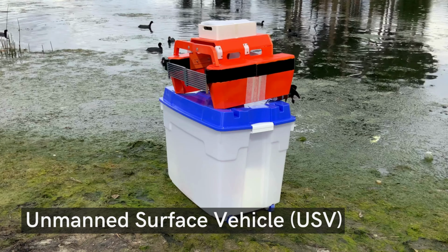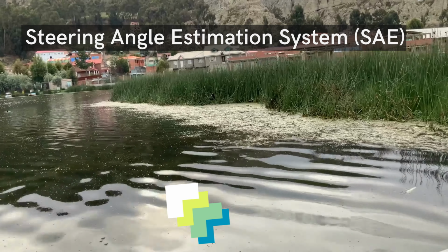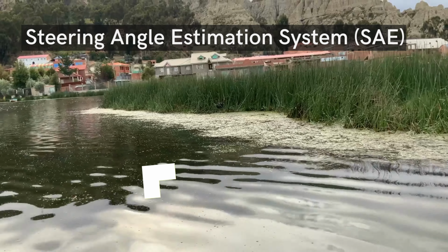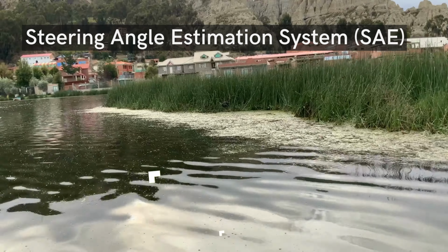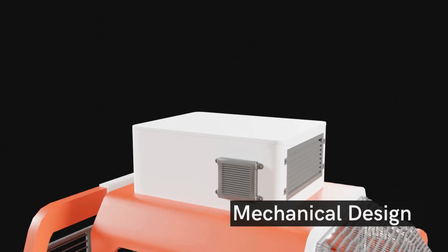With this goal, we implement and deploy a steering angle estimation system to process RGB and stereo vision data coming from an OAK-D camera in real time to collect duckweed colonies and avoid collisions. The mechanical design of our device consists of two floaters that are joined with a central structure. This serves as a support structure for a superior case where we save the electronic components of the device.